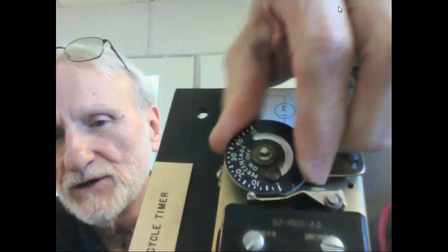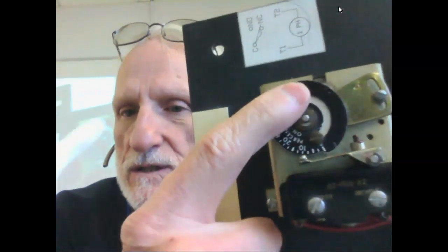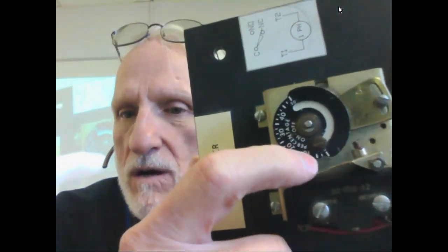And I think it's geared. I can't turn it. And notice it's got an adjustment on it, so we can actually adjust the gap here. This is called a cycle timer because it sits there and runs, and it creates a certain type. It's going to be on for a certain amount of time and off, and it's going to constantly switch between on and off and on and off. So this is the cam operated limit switch. This is the actual limit switch, and this right here would be the cam.